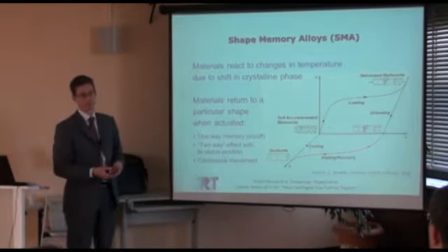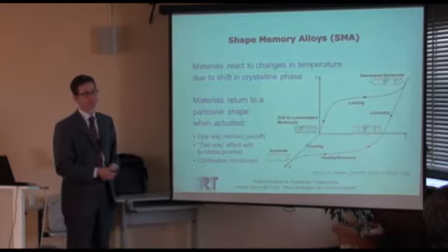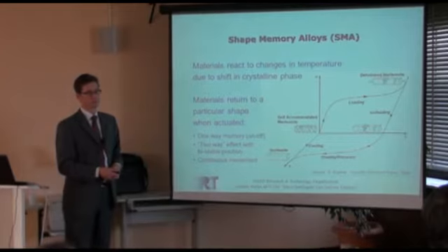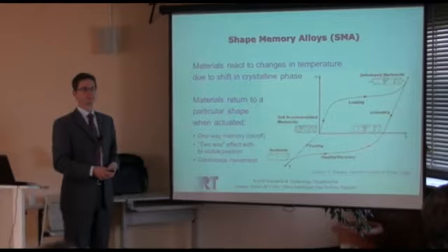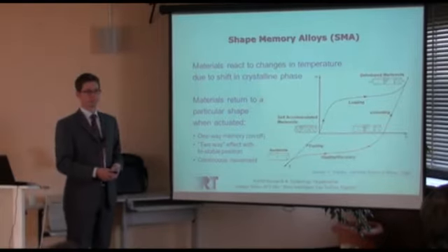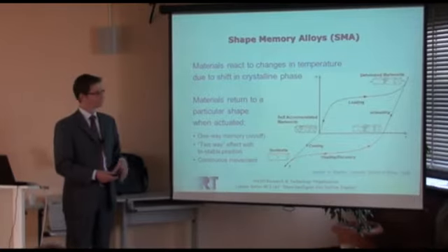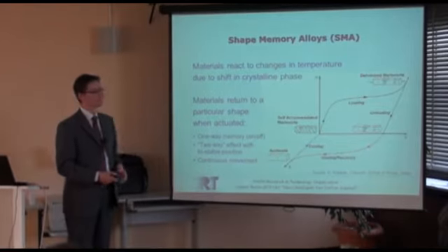What we have seen yesterday on the serrated chevron nozzles, they do heating for moving it inward into the flow, and the stable cold part is then withdrawn from the flow. It will remain there without being heated, but to put it into the other state, you have to heat it and maintain the heat. And when the heat goes away, it returns to its original shape.